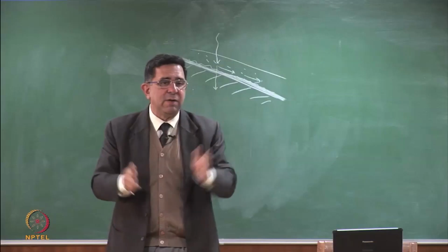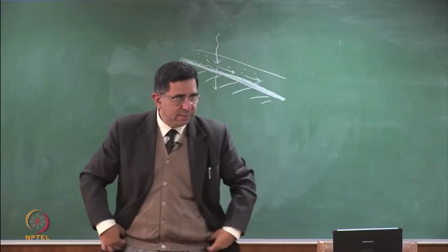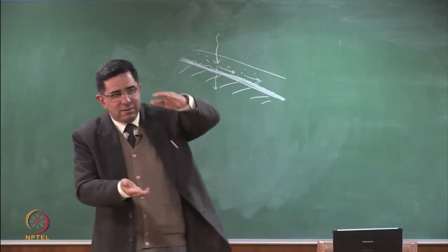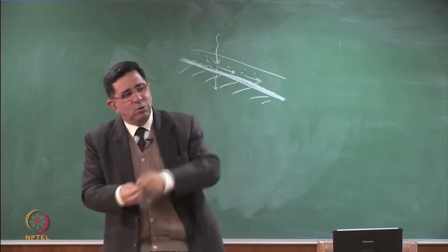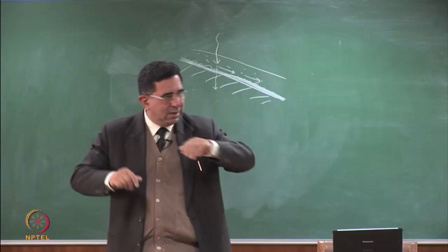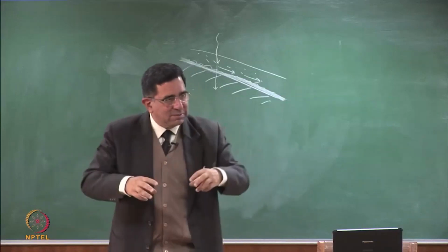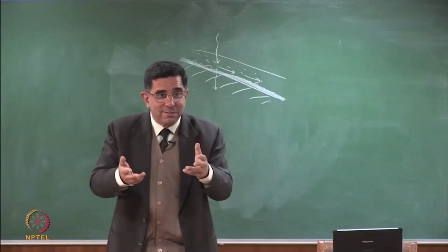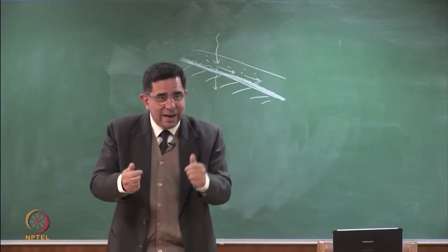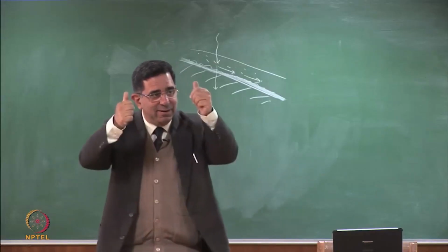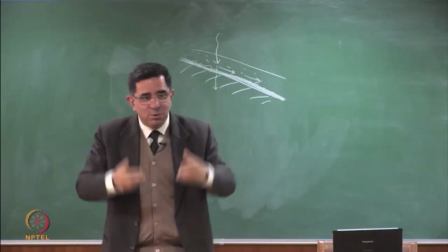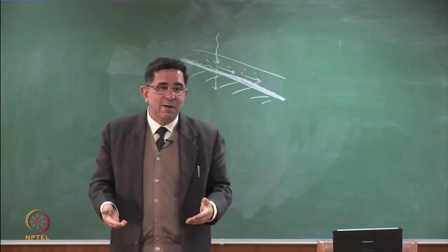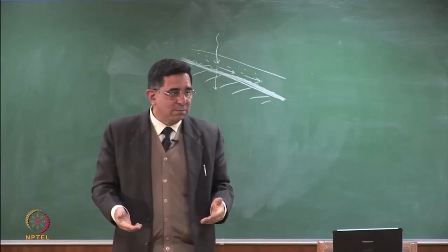Let us say I'm going to have 100 mm of rain. If I can design the soil such that this 100 mm of rain never goes through it, it falls, it runs off, whatever comes inside is held as storage, and then the plants give it back up. You don't let the water reach the bottom.